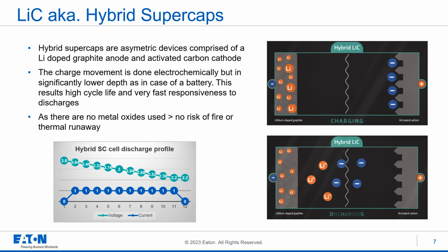In terms of performance, the device falls between a supercapacitor and a battery. However, the linear operation region on the cathode side gives charge-discharge cycling, temperature, and lifetime characteristics closer to a symmetric supercapacitor. Thus, in normal operation, it has a linear drop in voltage under constant current. However, there is also a minimum operating voltage to stay in this linear region in order to keep a long lifetime. Over-discharging the device below its rated minimum voltage will cause an accelerated degradation as the lithium is leached out of the anode.